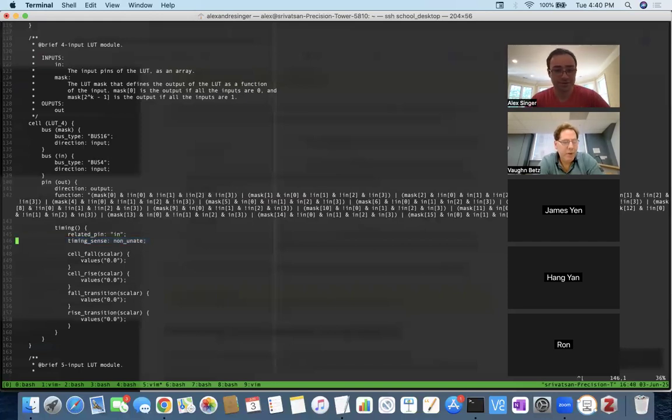It's also interesting that it actually is paying attention to the unateness, because when you give it the function, it technically should be able to figure it out. That may have come before the function. The experiment of making this positive unate happened before I actually wrote out the function in its entirety. You can kind of cheat here by just taking the AND of all the inputs and having that, and then making this non-unate, and that will technically work. But actually writing out the full function, I found, is much safer, and the solutions were always correct now. So what we have here is always correct. Yeah, so if you write the function, it should be able to figure out whether it's unate or not.